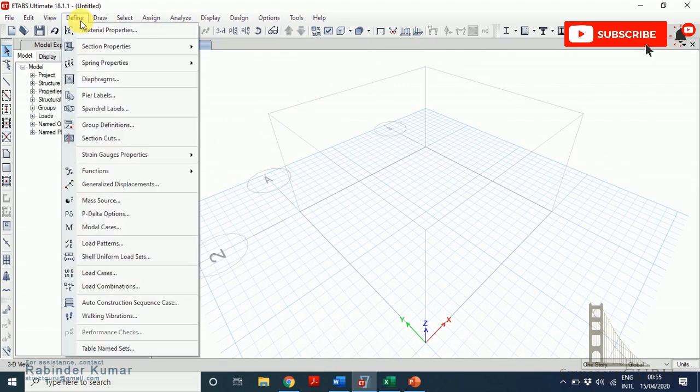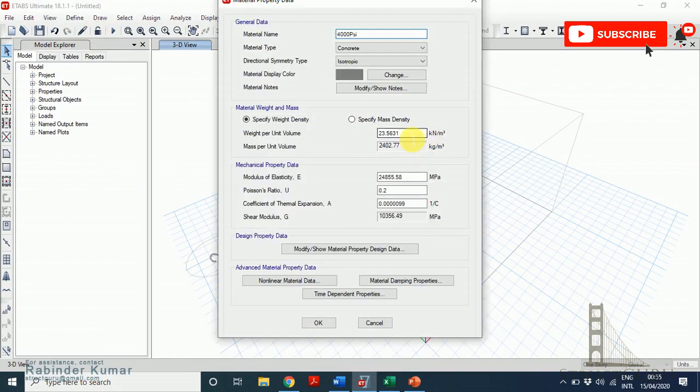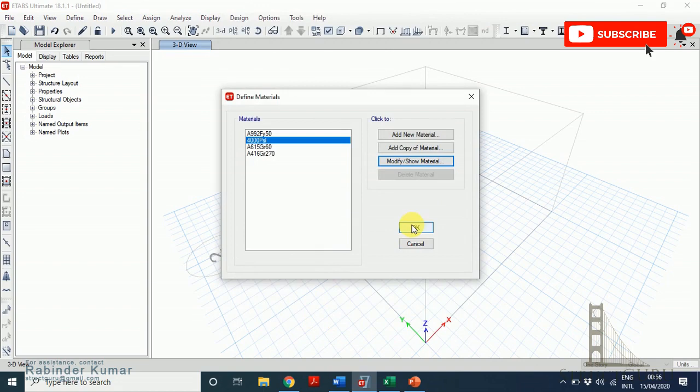Go to the define menu, select material properties, modify/show material. I am changing the density from 23 to 0 to avoid the self-weight of the material. So make it 0. Also, set the modulus of elasticity to 2 into 10 raised to 6, or 200 GPa. I will tell you why I changed this modulus of elasticity. Click OK.